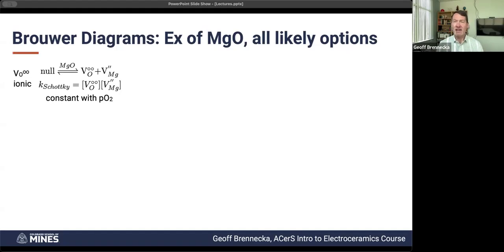If you've got complex three-dimensionally connected phases, the low permittivity phase and the high permittivity phase, the overall permittivity is going to vary with the mixture of those. When they're purely in series, that's when a low permittivity phase will dominate. And so hopefully you don't have a sample that has a completely open porous layer between one electrode and the other electrode if you're making a capacitor like Shannon suggested there. But that would be the case where that porosity would totally dominate. Hopefully that was kind of clear.